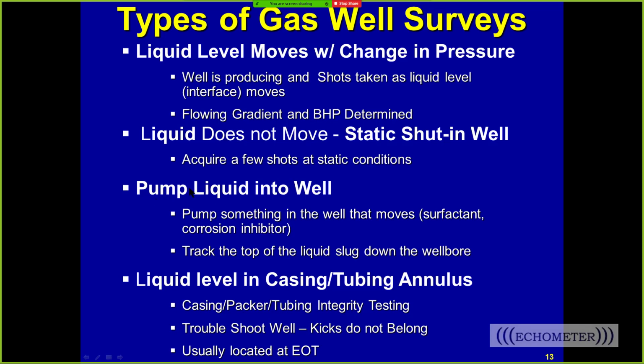And what we found, but we won't talk about this in this presentation, is that if you dump some liquid surfactant into the tubing, it falls very, very slowly. Initially, maybe 3 feet per minute, and then in the first 45 minutes, it'll fall less than 50 feet per minute.